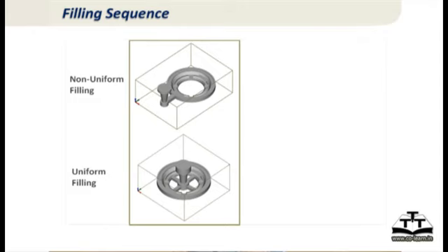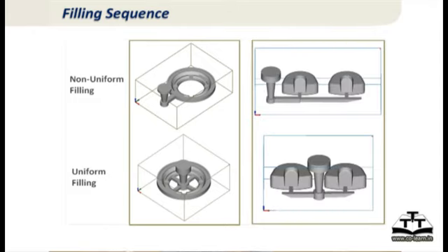And for the filling sequence itself, the last thing we mentioned is making it more uniform. For your wheel casting, instead of putting the sprue outside, if the wheel is big enough, you can put the sprue in the middle and then put 4 gates directly, no runner required. Much more uniform filling of the cavity and much better yield also, because you're not wasting the runner volume.